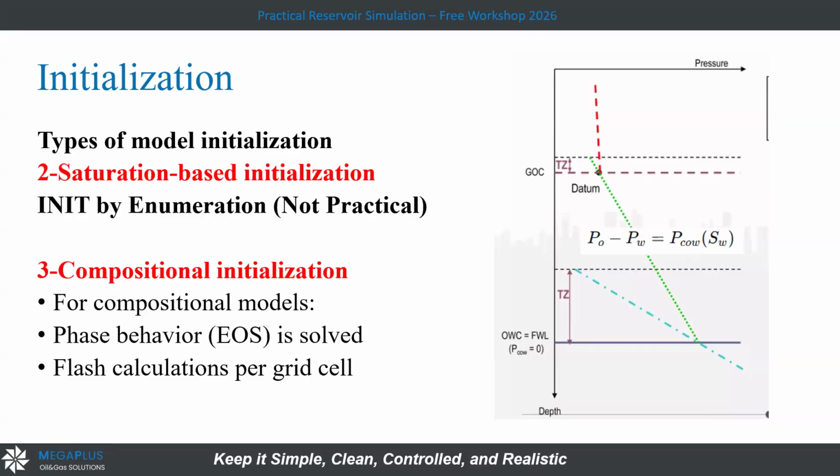So the model must understand very well the time step and the pressure at which the composition will change to form this condensation. You will see, as an example, something called condensate banking and liquid dropout. With pressure depletion, some condensate forms in the reservoir near the wellbore, and it will cause a lot of skin and a lot of production loss. So I have to manage this, and I have to simulate this.